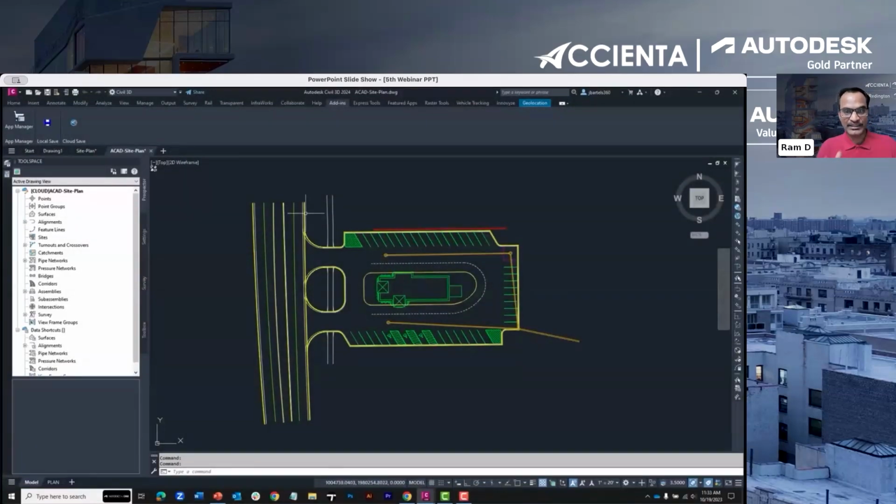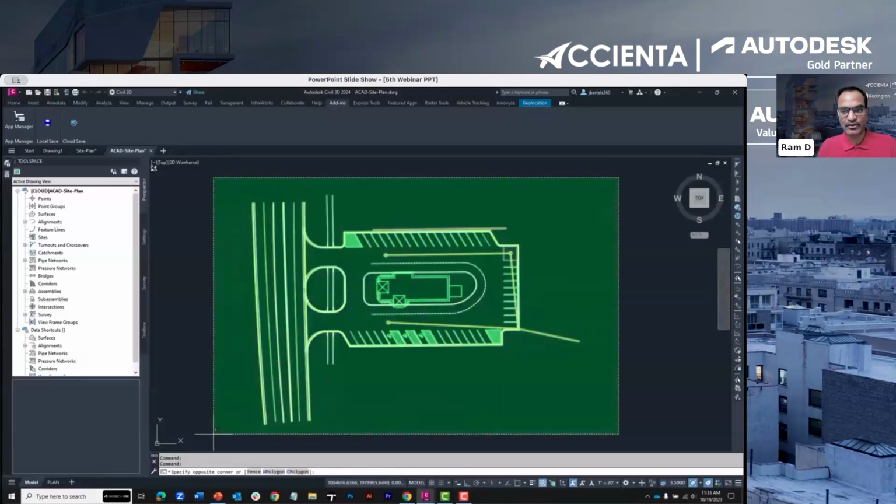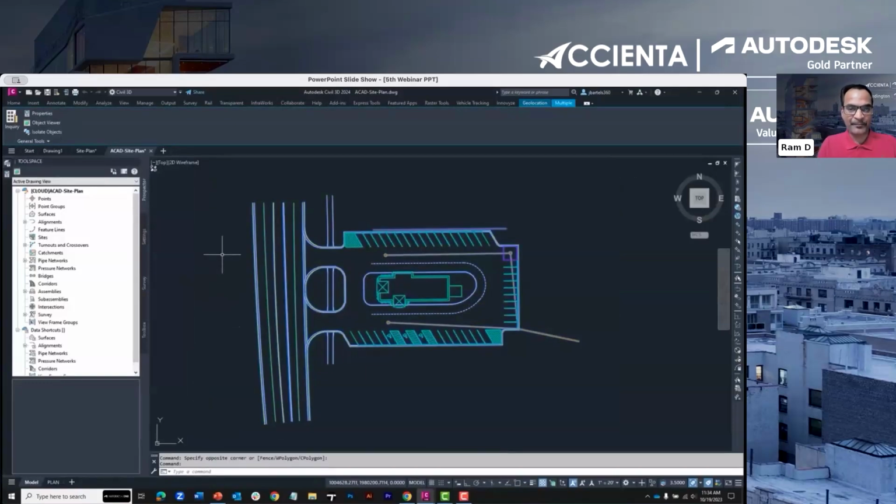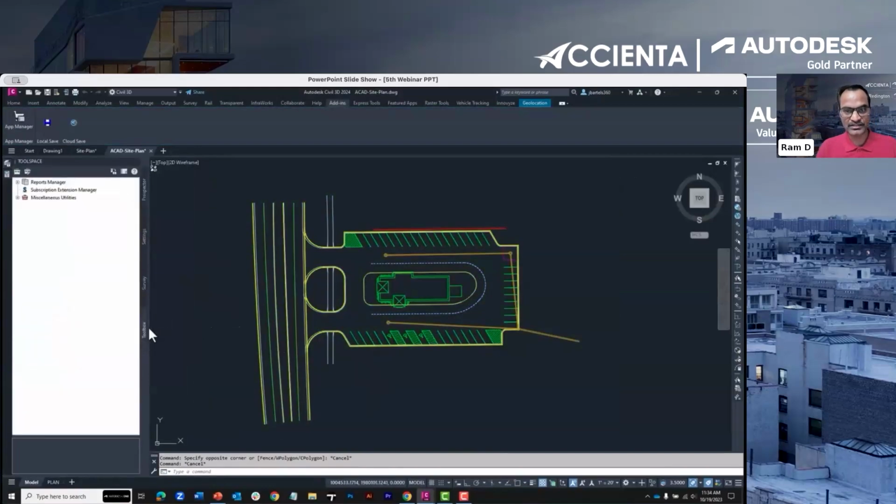So what happened here is within that Civil 3D, you have the inbuilt feature which is called geolocation. If you can see on the top right corner, the geolocation is already selected. And once the geolocation is selected, it will give you the option of retrieving the map, whether it can be from Google map or from Bing or from the real-time data. Or if your organization is using the ArcGIS application, that is also well suited for these Civil 3D drawings along with those Google features as well.